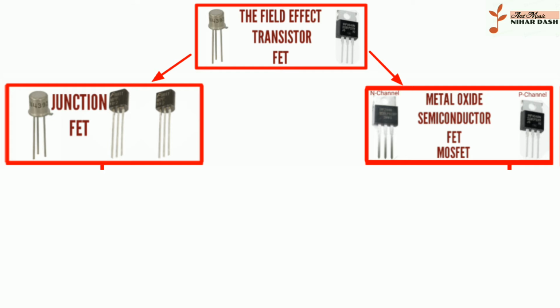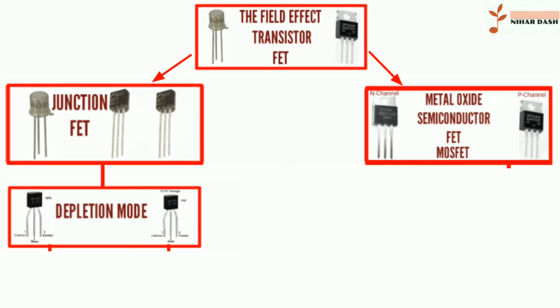The semiconductor material in a JFET is positively and negatively doped and arranged to form a channel for effective functioning of the device. Junction field effect transistors, JFETs, are depletion mode, since the gate junction would forward bias if the gate were taken more than a little from source toward drain voltage. Such devices are used in gallium arsenide and germanium chips, where it is difficult to make an oxide insulator.